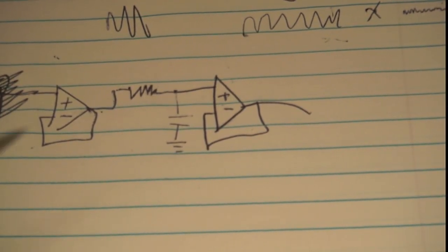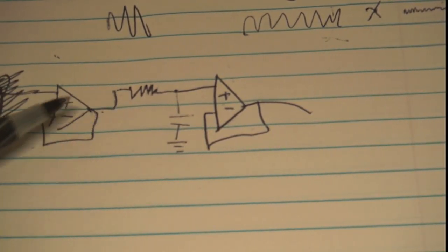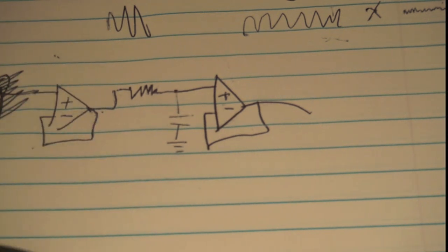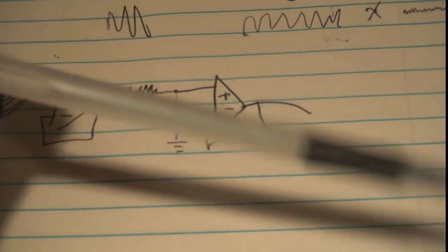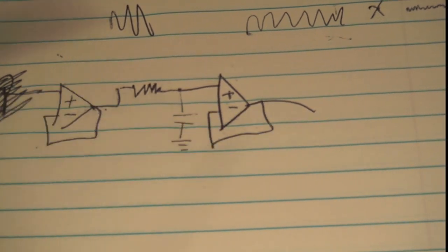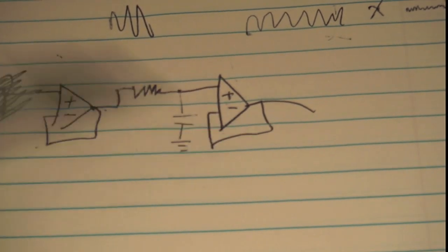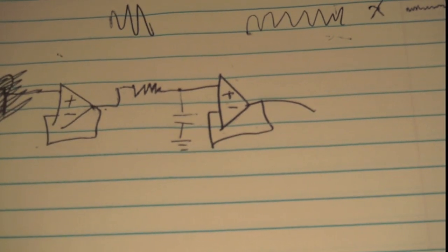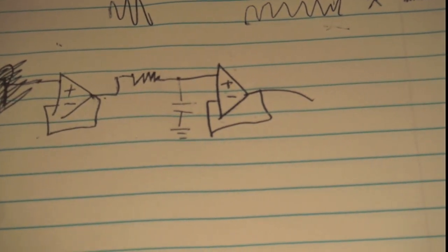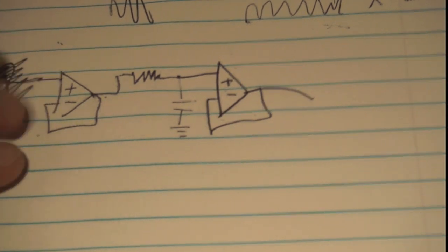So you drive the input so there's no extra resistances on the input from your power supply, capacitances from your power supply or whatever, and on the output so that your load resistance and load current doesn't load down the filter and change its cutoff frequency. So that's really going to be the basic design of our low-pass filter that we're going to build today for the first part of the series.